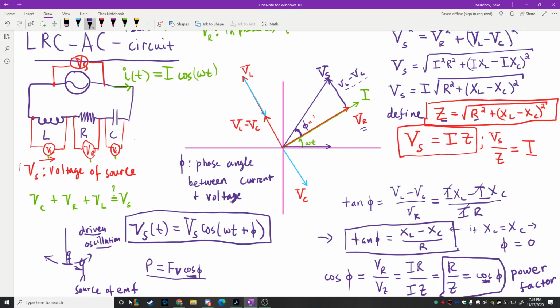Oh, one other thing to say here is this equation, Vs equal to Iz, even if you talk about RMS values, you get the exact same equation. So if you do V_RMS, that's going to be equal to I_RMS times Z as well. You get the exact same equation. It doesn't really matter which one you choose. That's not going to be true for everything, but this one it works because to get the RMS current, you just divide the left and the right-hand side of the equation by square root 2, and immediately that gives you this one here. Same thing can be said for this equation. We could do the RMS on both sides if we want to as well. No, that's not true. Not for this one, but...